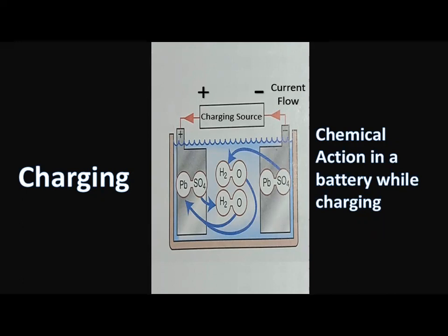When a battery is charging, hydrogen gas escapes at the negative plates and oxygen gas is given off at the positive plates. When combined, these two gases form H2O. Because of the possibility that not all the hydrogen gas will have recombined with the oxygen to form water, caution should be taken to prevent sparks near a charging battery. The SO4 is always on the plates or in the electrolyte.